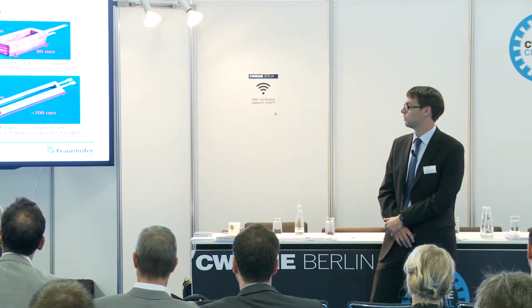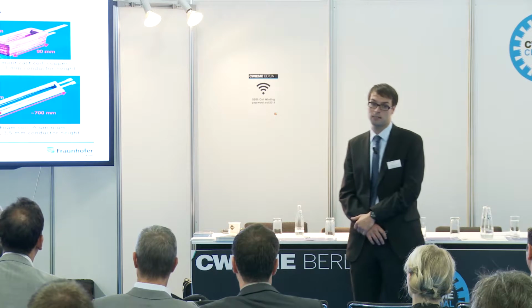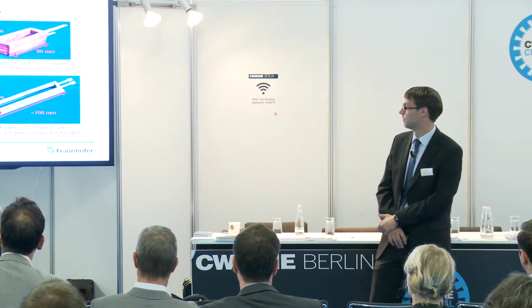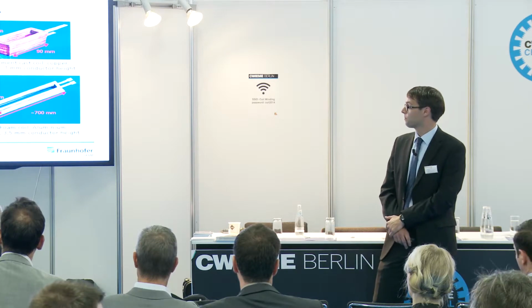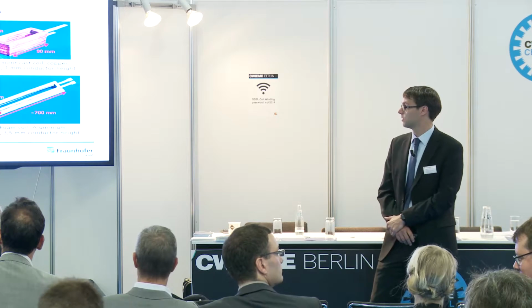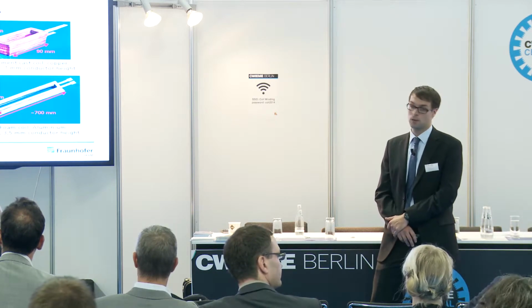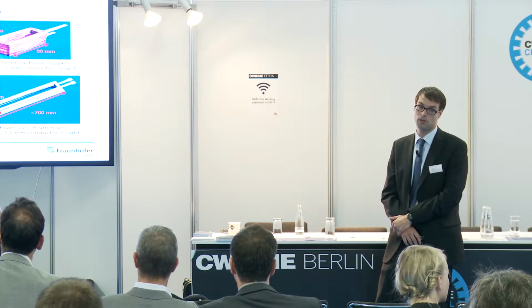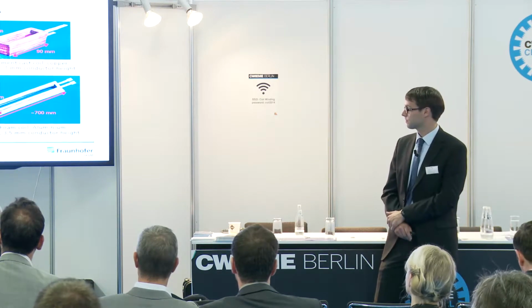For very big coils, we can realize lost foam casting. It's another casting process based upon lost models. We can realize coil lengths up to 800 millimeters, areas about 20 square millimeters for very big coils, for example, exciter coils or large DC machines.